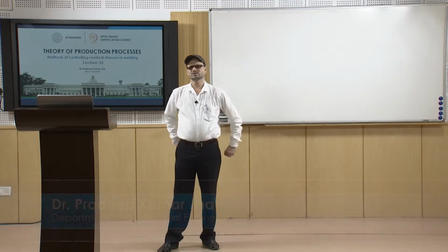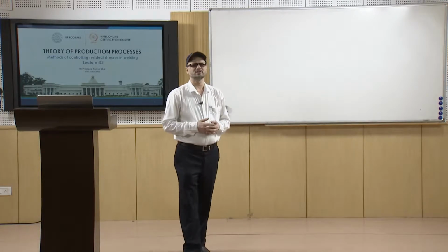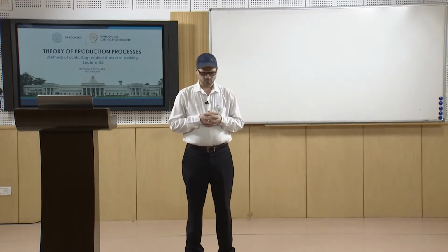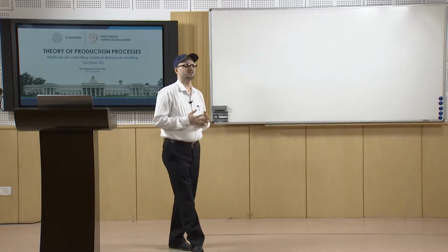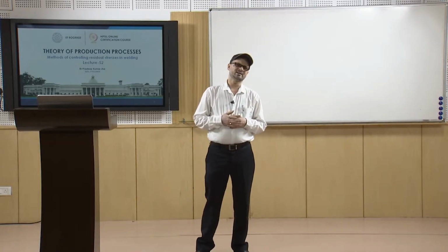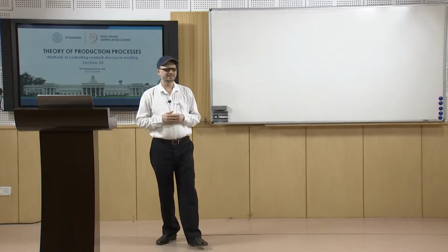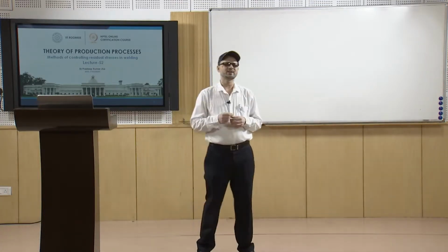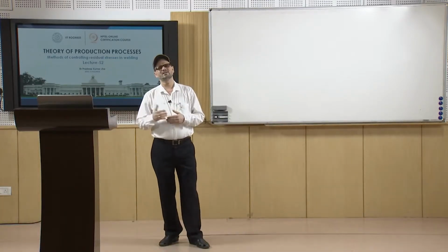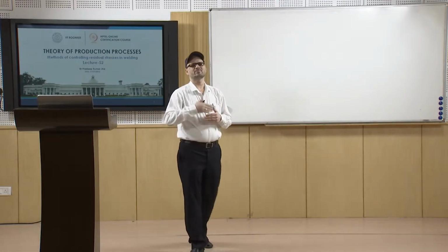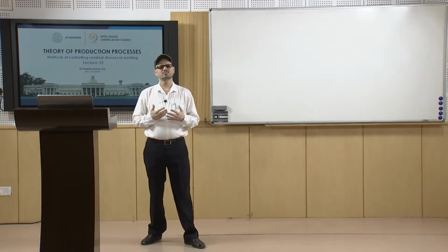In the last lecture we discussed the different types of residual stresses which occur in welding, and we also discussed that residual stresses may be beneficial in certain situations and may not be in others. Especially, if they are compressive in nature they may be more beneficial in certain aspects, but when they are tensile in nature and of a larger value, they are detrimental to the performance of the component.